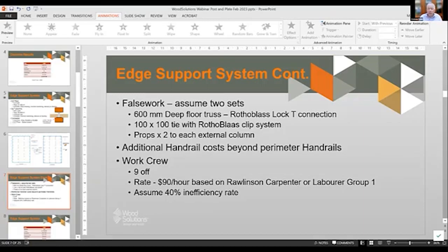And interestingly, and we debated this at our workshops, we just didn't use the program time. And I can tell you, Perry and myself debated that program time till the cows come home, but we put in an inefficiency rate of 40%. We originally had a 50% inefficiency rate, but our tier 1, tier 2 contractors said we were too harsh on ourselves, so we reduced it to 40%. But there's inefficiency, and that means when the crane's idle or something's happened or the wind comes up, whatever it is, it accounts for those things, and people going off and on the building during the day.